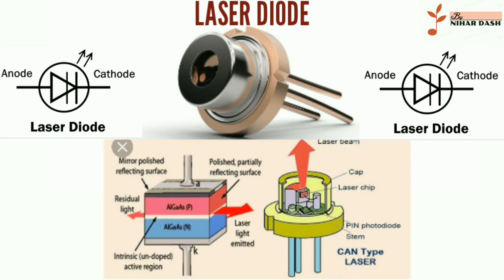Moving further, now understand the process of spontaneous emission. Spontaneous emission in laser diode. Due to absorption, the atom is present in the energy level E2. So, as the lifespan of the atom expires, it now comes back to the ground level from the higher energy level. On coming back to the ground level, the atom emits the energy difference of the two energy levels, i.e., E2 - E1. This energy is emitted by the atom in the form of an electromagnetic wave, generating a photon of energy. This process is termed spontaneous emission. This radiation emission phenomenon is usually seen in optoelectronic devices, such as LED.